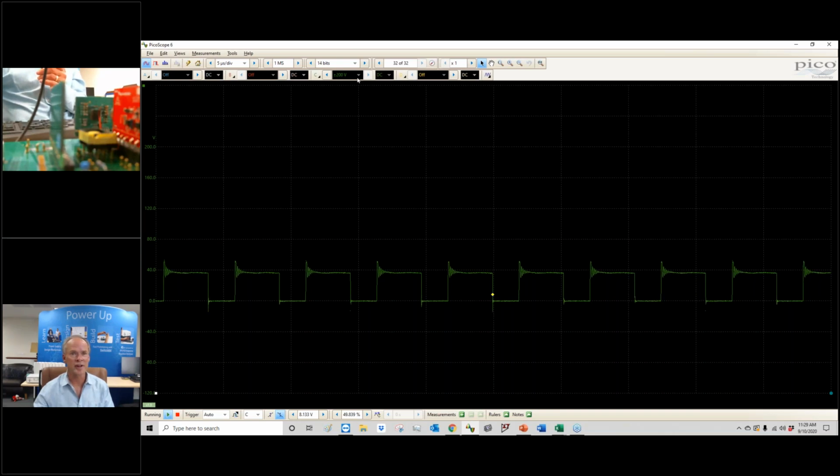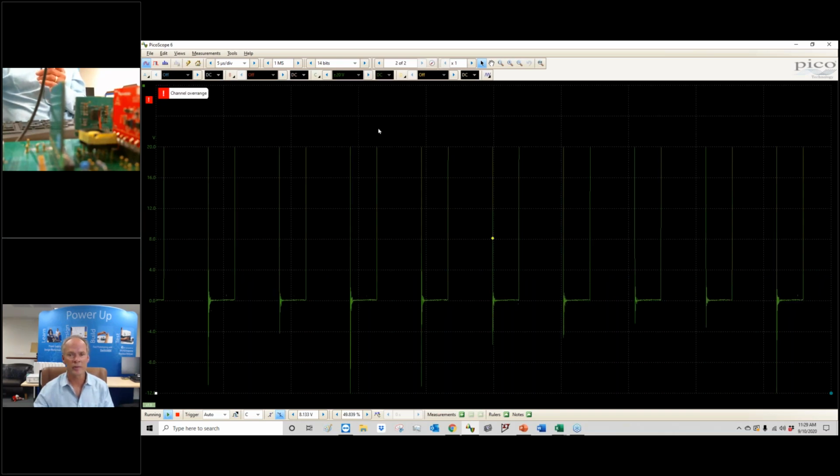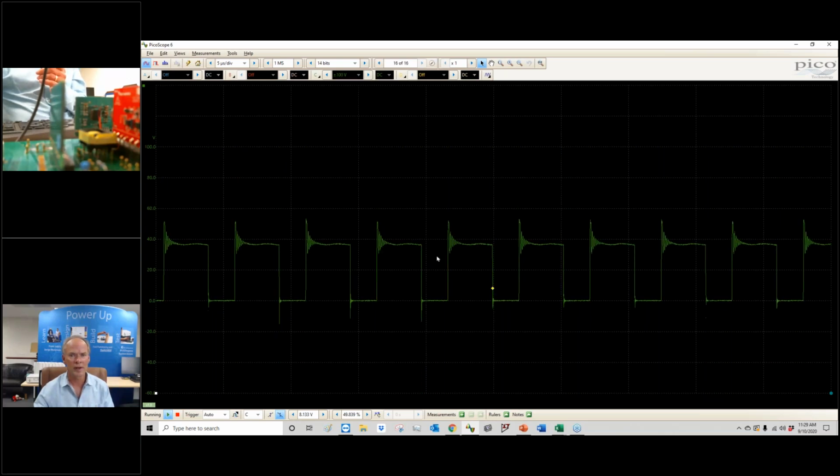You look at the waveforms on the screen right now, we don't have our snubbers in place here on the primary side, so we haven't taken care of this ringing. This will affect things. Even though you don't need it for stress, you damp the ringing because it will come and get you either audibly or in the EMI signature when you move on to that part of the design.